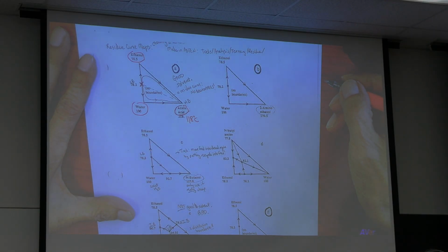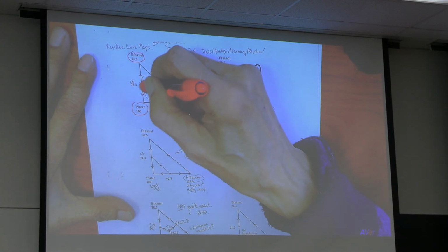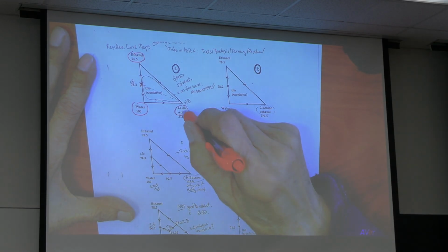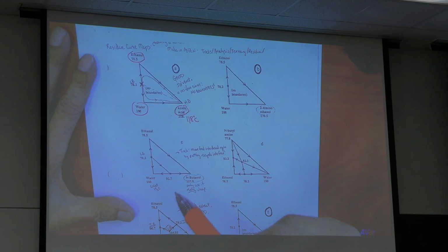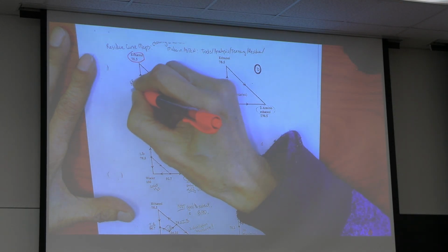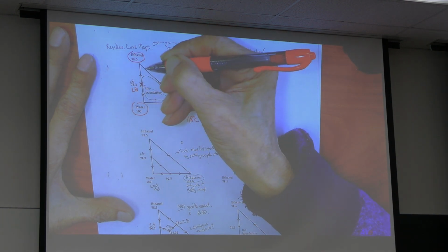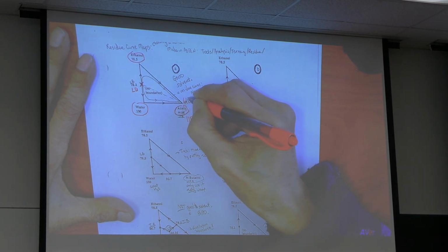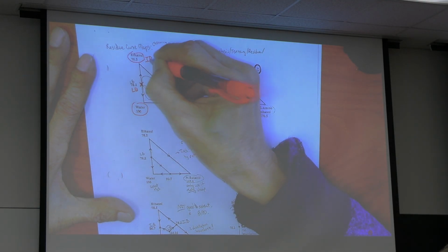So you go to Aspen, you find out 3 pure component boiling points plus azeotrope. This is the feasible and good solvent. Why is that? 78.2 is the lowest boiling component. 118, highest boiling component. Intermediate.